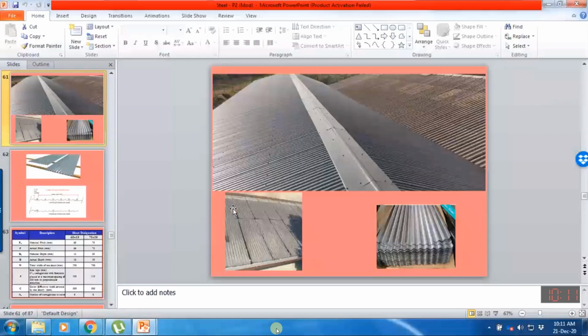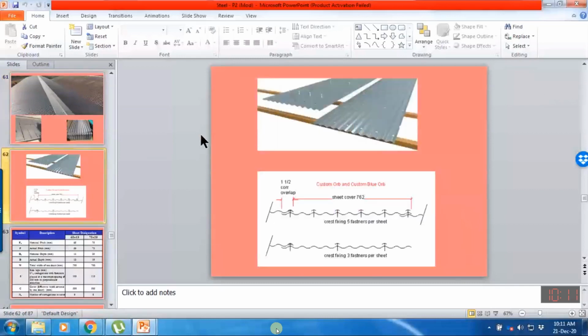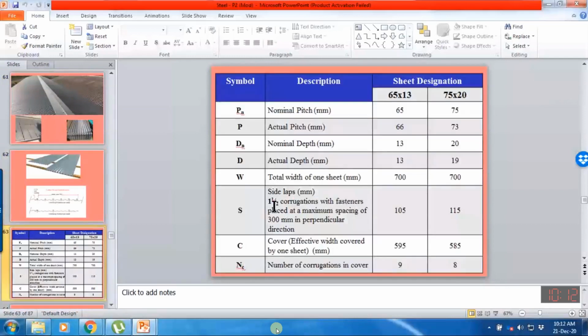For example, here you will have a better idea. In this direction, we are connecting with the purlin. So they can also be evenly divided. Along the purlin direction, we can also maintain this distance of 200 millimeter. Any distance less than 200 millimeter can be used, so that is not related to the strength criteria. And further, maybe there is also something in the next slide.